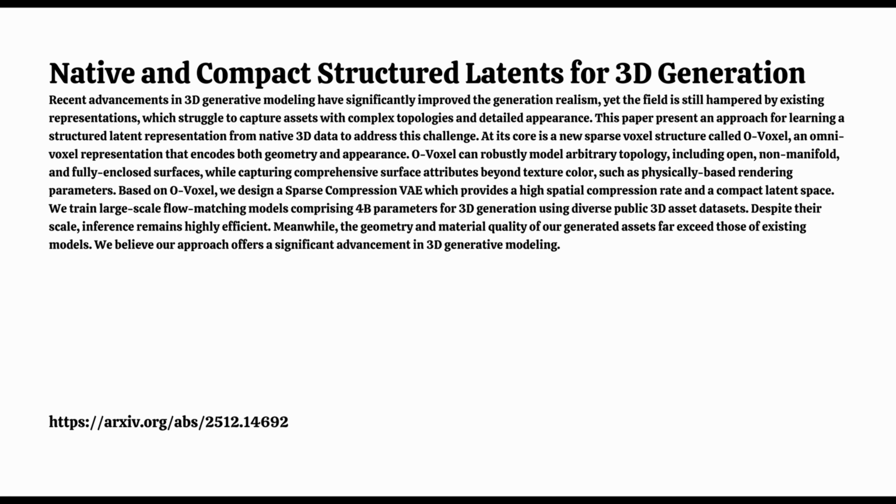Okay, so if it's not reading a field, what is it reading? It goes right to the source, the input asset's mesh surface. It uses that mesh to determine intersection flags for the edges of the voxels, and it assigns what they call Hermite data. Which essentially gives us two pieces of information at the intersection points: the exact location of the intersection and the surface normal, which is the direction the surface is facing.